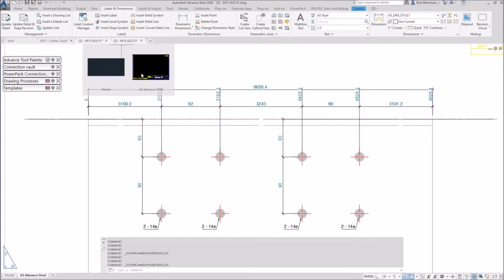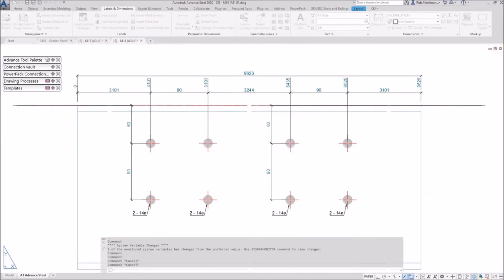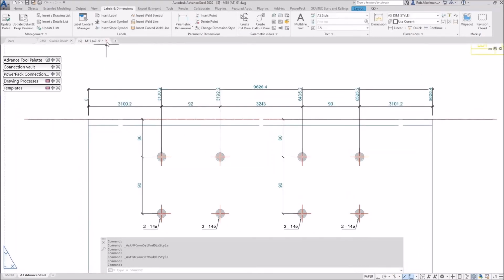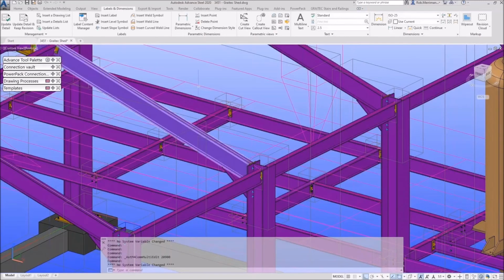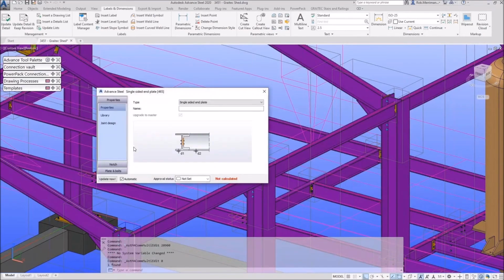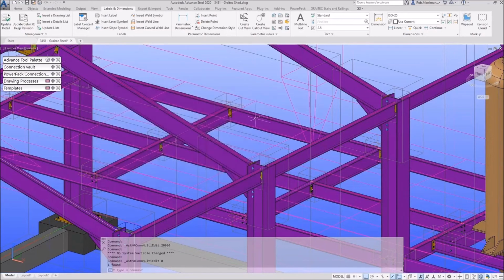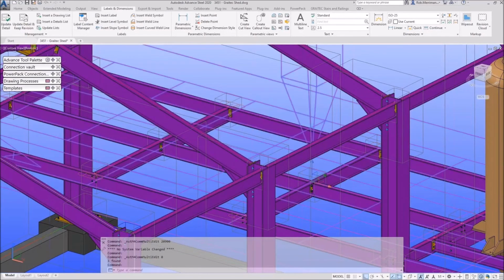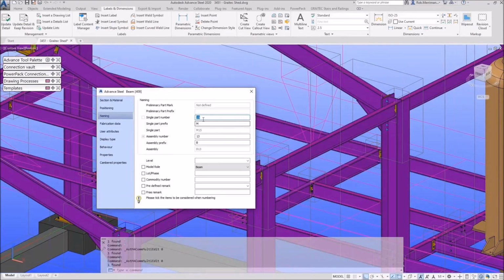So it's M15 and it's the holes in here. And again, I have just been messing with the bolt centers. So it is this connection in here. Horizontal bolts, I set those centers at 92. So that's why I'm getting different parts. Please never manually come in here and override this number.